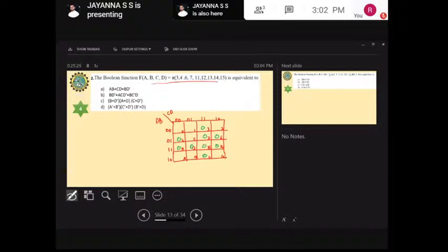Now I am going to map this. I am going to look for powers of 2. First I look for 2 power 4, 16, since it has 4 variables. Can I make that one? Then 2 cube: there are no 8 successive zeros here. Then 2 square: there are 4 successive zeros. I am going to map those.